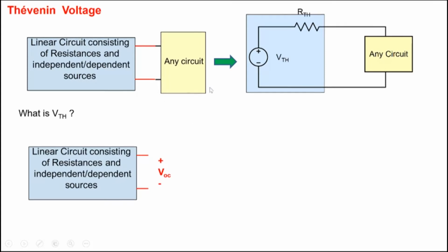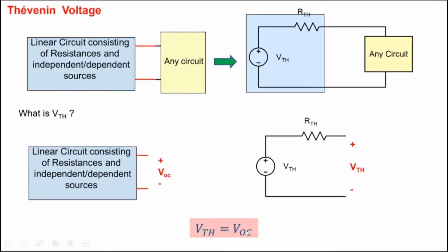All right. Now, these two circuits are equivalent. So let's open it up here also. Let's break it up at this particular part. So it is broken here, and they are both equivalent. So the voltage here, we know that once you open it up, is going to be VTH because there's no current flow. It's an open circuit, no current flow. So it's basically equal to VTH. And the two circuits are equivalent. That's what we want them to be. Which implies that VTH equals VOC.